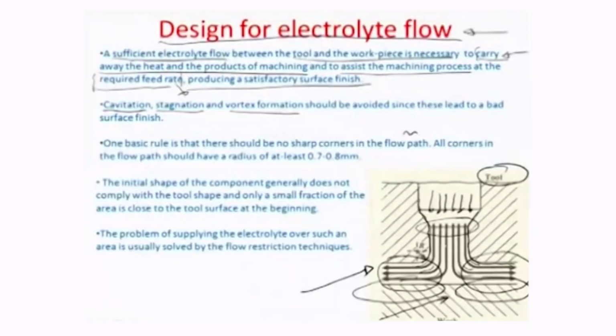So, supposing there are certain nooks and corners in the workpiece where sometimes because of extremely low, let us say, discharge rate, the perfect streamlining happens. So, supposing there is a surface like this that you are trying to machine with this tool, okay, and this tool is shaped in this particular manner with the electrolyte flow across the center of the tool concentrically.